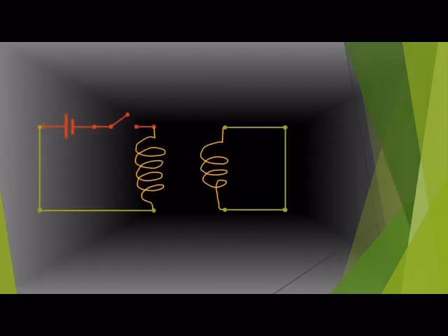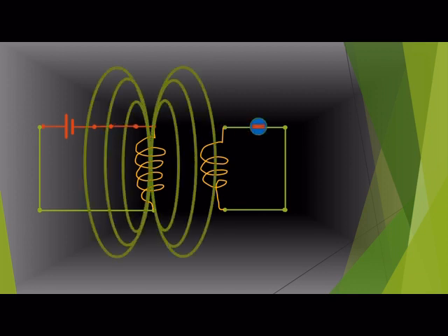This is the principle behind induction heaters. Consider two coils, one connected to a battery with a switch and another connected to a current sensor. When you turn the battery on, the first coil has current flowing through it, which generates a magnetic field. The second coil, which had no magnetic field, now experiences a magnetic field, which is a change.